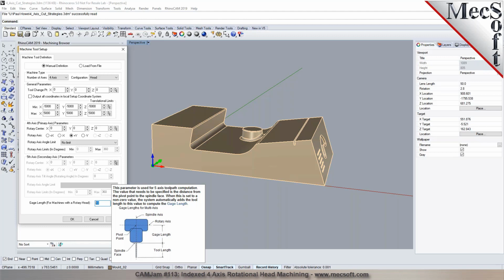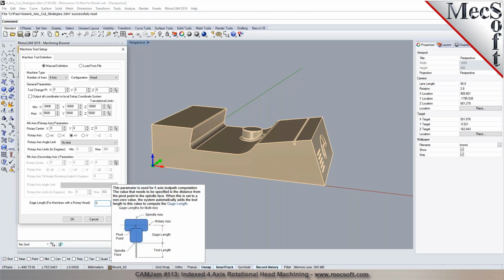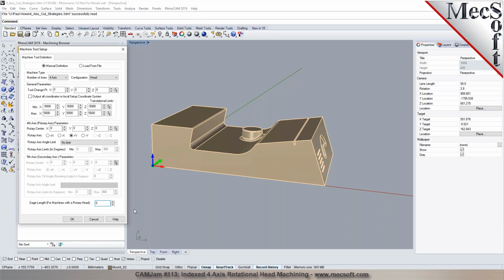Okay. That parameter will be constant for a given head on a CNC machine tool, but the variable would be the tool length, depending on the size of the tool you're going to be using and how far it's sticking out from the spindle face. Okay, I understand that. If you put this value to 0, it means the controller does the compensation, so we don't have to compensate from the CAM product here, like RTCP on, or certain controllers call it RTCP or G43.4, or G48.1. Each controller has its own way of handling it.